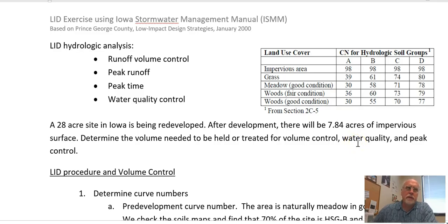water quality. Recently, here nearby in Harrisburg, Pennsylvania, one of our student project teams is working with an organization that has a drainage issue, and they designed a rain garden, but the main constraint for their design was that it had to be designed for water quality. So there's guidance out there on how to size various BMPs that will improve water quality.